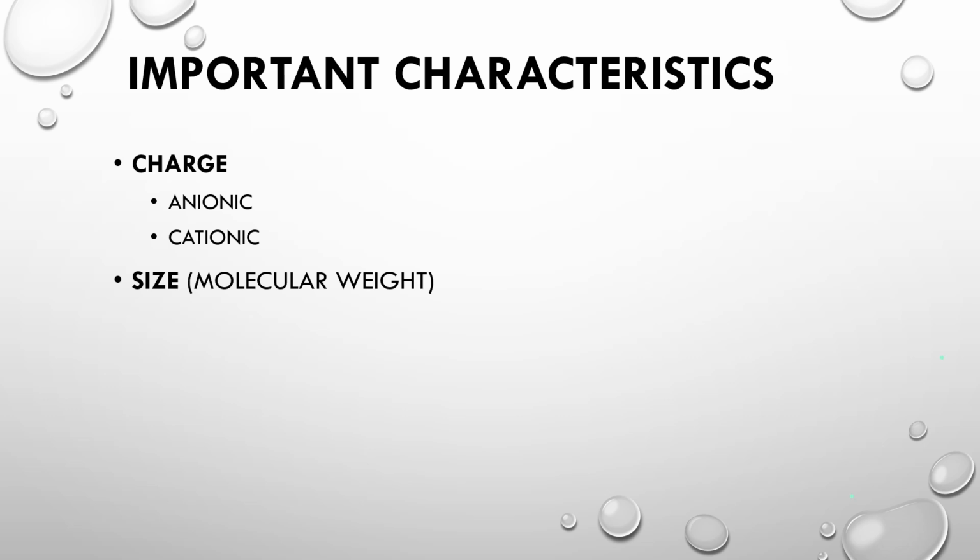Now, cationic polymers, those are positively charged and will bind to the gill surface of aquatic organisms and cause suffocation in a very low amount. So they have a high aquatic toxicity. This is why charge is so important and why we only use anionic polymers for these environmental applications, is that they're going to be safe for fish. Now, cationic materials can certainly be used and they're effective for water treatment, but they're typically limited to active treatment systems where we're going to use filters and monitoring and things of that nature.